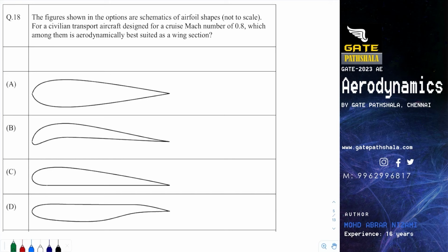as a wing section. Different aerofoils or shapes are used in different categories, but if you look at the Mach number that they have given, it's not a low speed Mach number, it's a high speed Mach number. Above Mach number 0.6 we consider all as high speed flows. Okay, not supersonic, but high speed subsonic flows. So locally the flow might accelerate and become supersonic, forming a supersonic bubble which would terminate into a shock like this, giving rise to shock induced boundary layer separations of this sort.